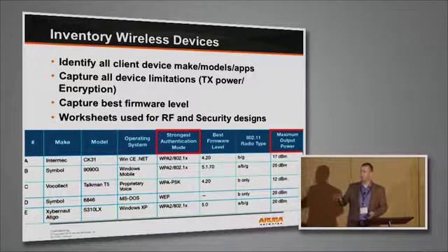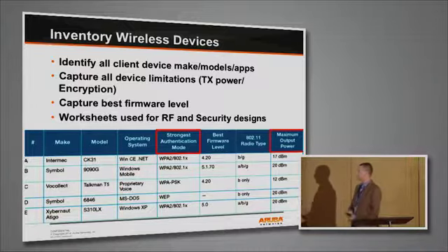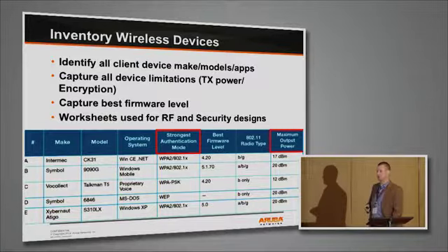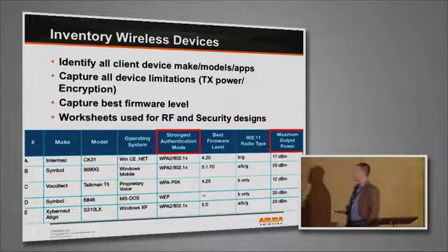I've had problems where you might run into Motorola 9090s in one site and there's the same equipment somewhere else, but I'm running into LEAP issues and it turns out to be a firmware issue. So if I can keep track of what firmware we've got out there, then it gives me something else to look into as I'm trying to narrow down problems. But I'll grab it all in the planning stage up front.